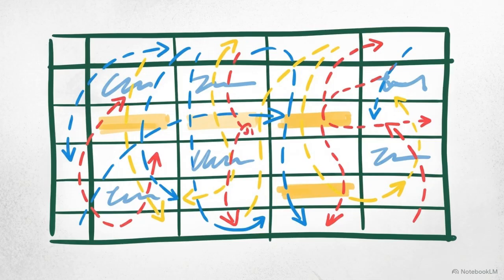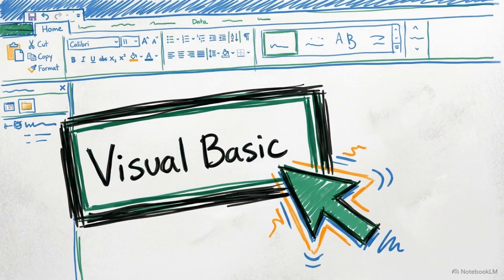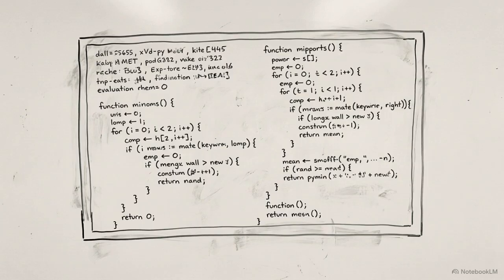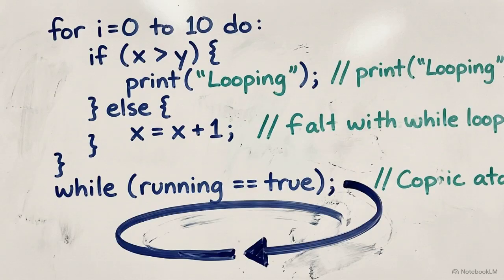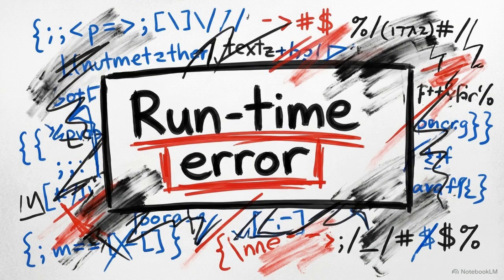Click your new Developer tab at the top of the screen, then click the Visual Basic icon. A new window will open. Insert a blank module and paste in the provided looping macro code. This script gives Excel a strict set of instructions. Recalculate the randomized variables, copy the final target output, paste that result into our historical tracking list, and repeat the process. But this macro will instantly crash if it does not know exactly which cells to copy and paste from.